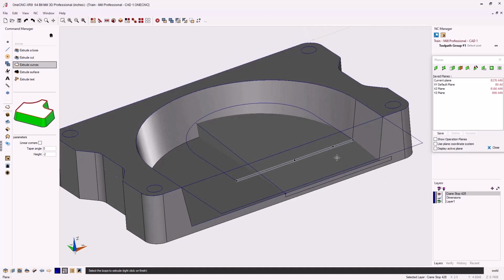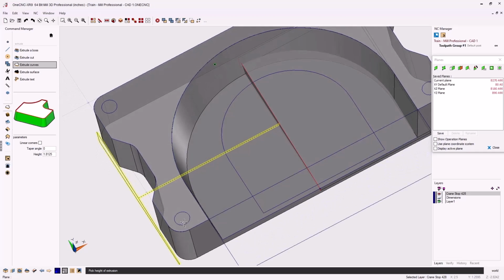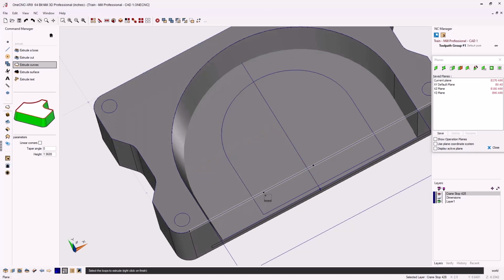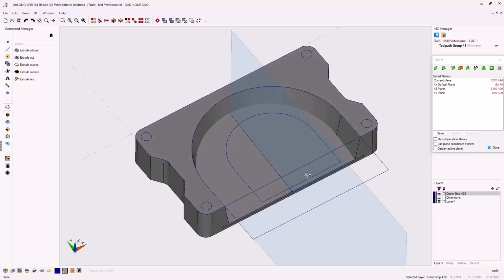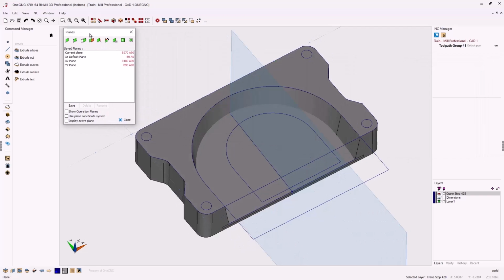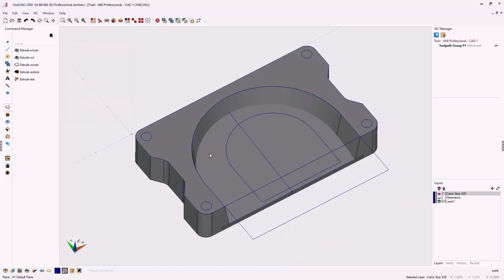Now let's create another solid model. Same technique, we're going to left click the boundary, right click, and pull the boundary right till we pass the end of the pocket cutout, right about there, and left click. When we're done we can right hand mouse click. Now we no longer need to use the new construction plane, so let's go back to our original default XY plane, and we can now close down our construction plane tools.